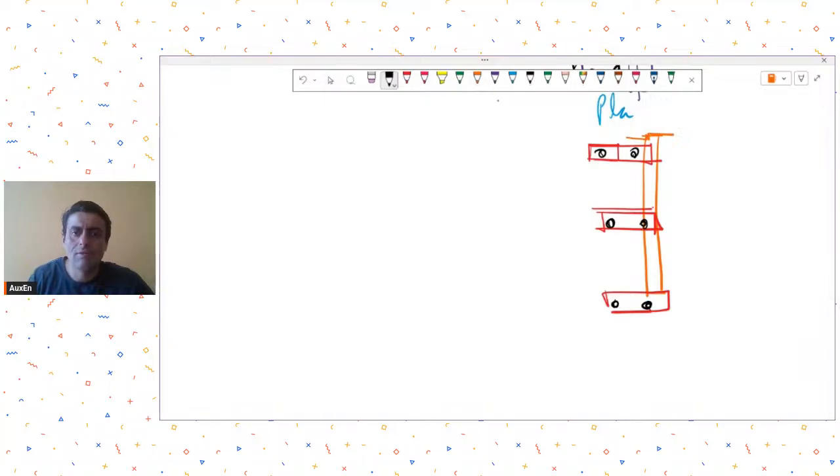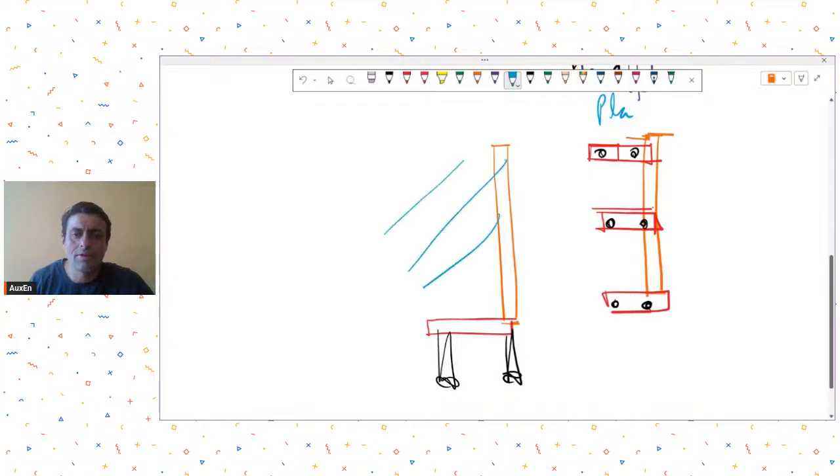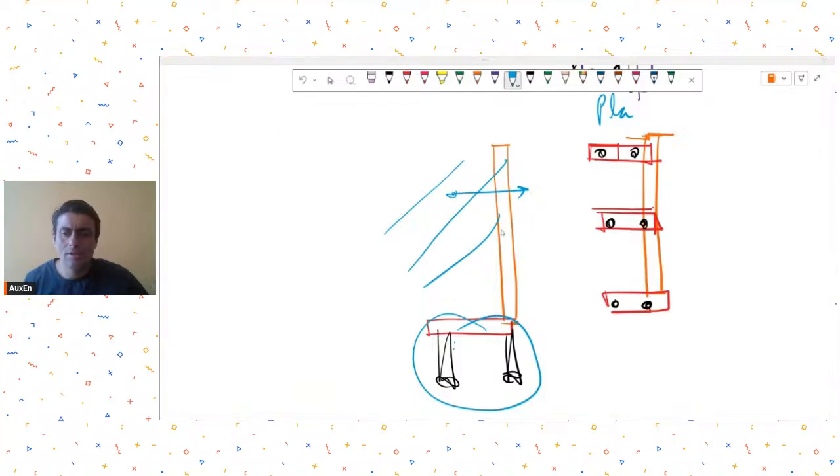So in sectional view, it will look like this, that this is your wall. I have not provided any toe, heel, or anything like that. So this time I'm trying to take the overturning moments of the retaining fill by this pile cap and piles. So whatever fill is there, it will be resisted by this pile only. Okay. So this can be one of the configurations that you can think of.